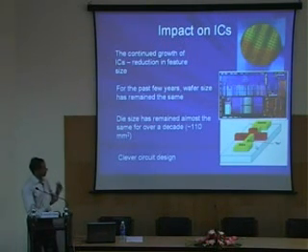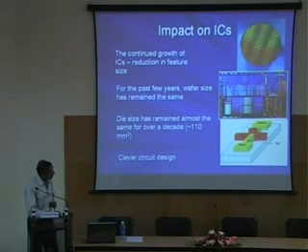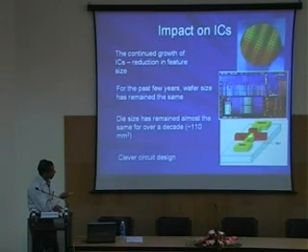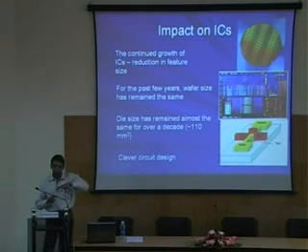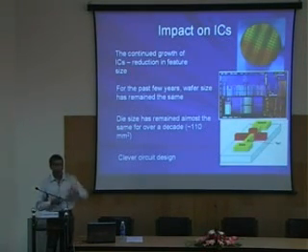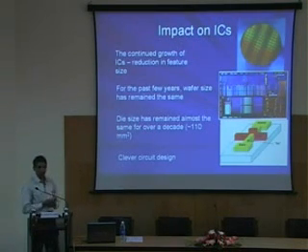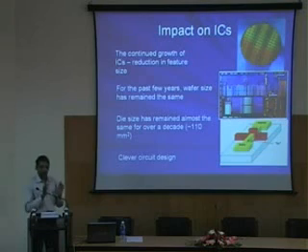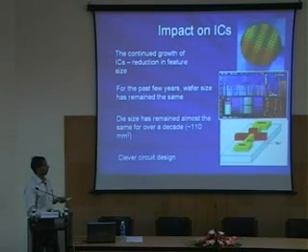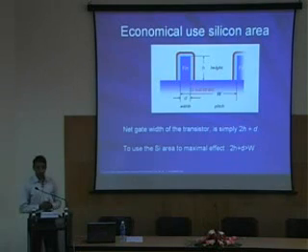The device that we use in today's CMOS technology is known as the FinFET. A FinFET consists of a silicon fin here, which is 5 nanometers in width, maybe tens of nanometers in height, and then you have a gate all around this fin. Because the gate is all around, you can effectively control the current flow from the source and drain. And if I had to take these nanowires as a replacement for these existing FinFETs, the nanowires must satisfy certain conditions. Whether we will be able to do that, it's not yet clear.